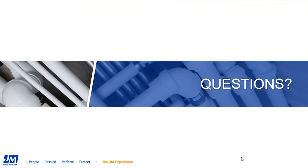Sure, at 25% compression. So the next one, John, I'm going to go ahead and ask you this one. When we talked about the Microlock pipe installation, in the top right photo, we showed a section of pipe that had been cut or filleted. This would, in theory, reduce the R value at that specific area and could lead to additional heat loss or condensation. How would we address that, and do we recommend full thickness everywhere across the entire pipe system?